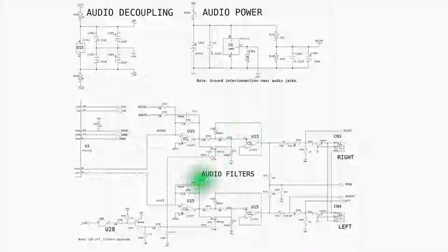We get into the actual audio section here. We have the Poly chip here, and we have the right and left channel outputs. And I think I mentioned this up above, this audio ground reference also comes from the Poly chip. So we've got our audio outputs. They come to an LF347 op amp.